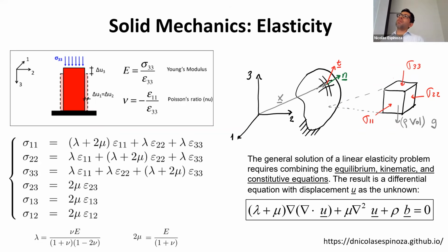That is what is built up in the geomechanics module of your reservoir simulation software or any continuum mechanics software. It is this equation over here. It may be a little bit different depending on the constitutive equation and the kinematic rules, but basically it is the differential equation that allows you to solve for displacement and tell what is the field of stresses in a particular location.